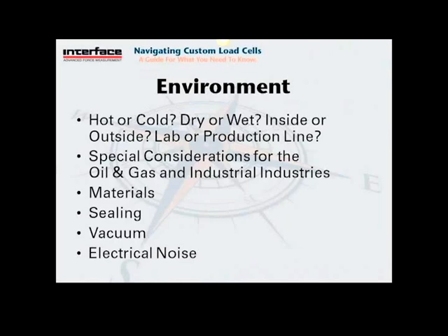Sealing of the load cell can be achieved through either bonding or welding of diaphragms to cover the gauge area so that it doesn't get damaged and to protect it from whatever environment there is.